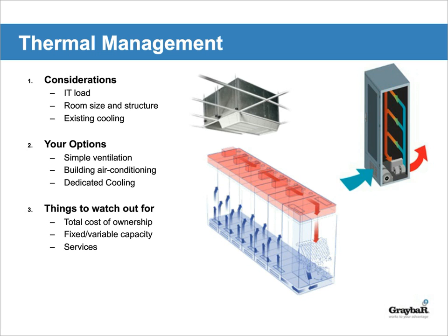You have to know how much heat that IT load is going to be dumping into the room. Then you need to understand the room, right, where the IT equipment is going. Is it a pretty small room with a low ceiling or a pretty big room with high ceiling? That influences your decision. And then you have to see how much cooling you already have in that room. And then you have to decide, right?